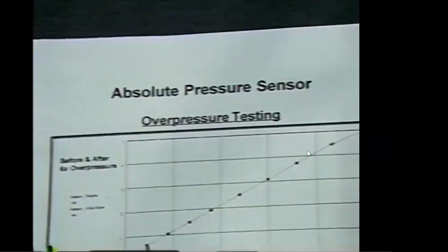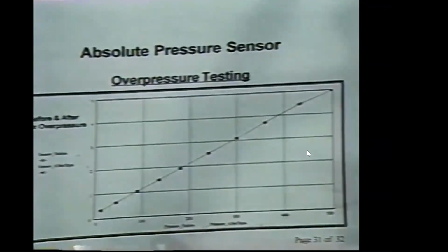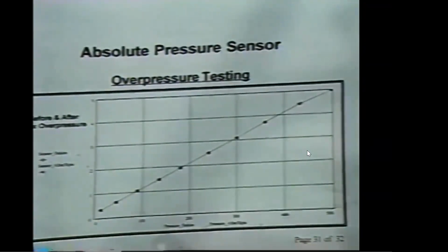An additional benefit of polysilicon pressure sensor membranes is that because the cavity is so small below the pressure sensing element, if you overpressurize by accident or intentionally, the membranes will bottom out at the bottom of the cavity without actually rupturing.